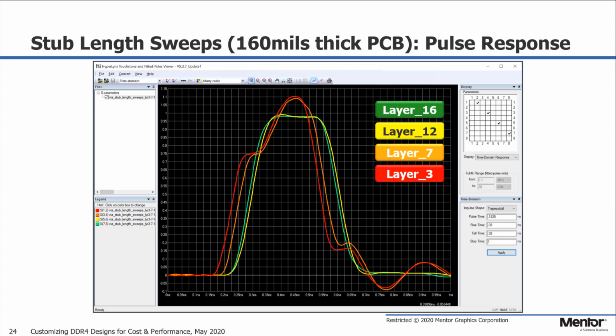So as in summary, we saw that the micro vias perform better than the through-hole vias. So now it's a matter of trade-offs between cost and performance. But apart from opening up the routing paths with micro vias, we also want to know how much margins you're gaining.